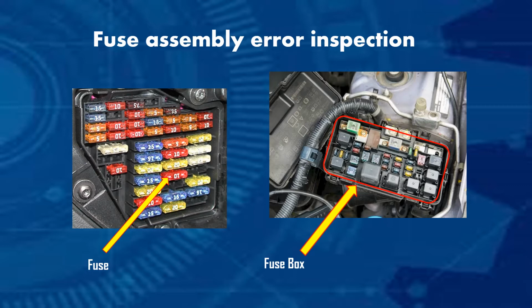Why is it important for us to know if fuses are installed correctly? Fuses will be able to handle different amounts of current, and that's usually noted on the fuse, somewhere with the number telling how many amps it can handle. If the amperage rating is too low, it will break too soon. And if the amp on that fuse is too high, components may fail before the fuse does.